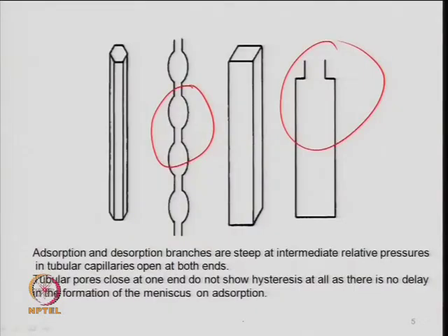There can be 5 different types of adsorption hysteresis, A, B, C, D, E, observed experimentally depending upon the type of the solid material. So, that is what I said, that the structure may be of different nature, hexagonal like this, right. It can be a rectangular channel and it can be ink bottle type, but in the ink bottle also, this radius, this length is larger compared to this neck length.